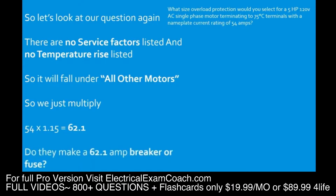Now, do they make a 62.1 amp breaker or fuse? No, they don't. So the question is, can we use the next size up? And the answer is no. With motor overloads, you are not allowed to use the next size up.